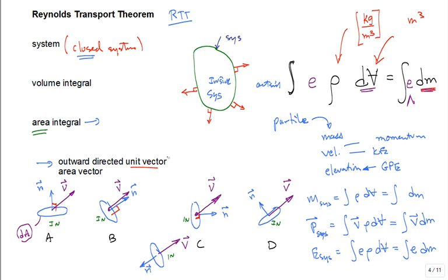Now, we have this idea of the little outward directed unit vectors. We also have the size dA. We have its perpendicular, and then we want to know, how do I mathematically compute this flow? If I take this vector V and dot it with n, that picks up the component of V that's in the direction of n. True? If I then multiply that by dA, what do I get?